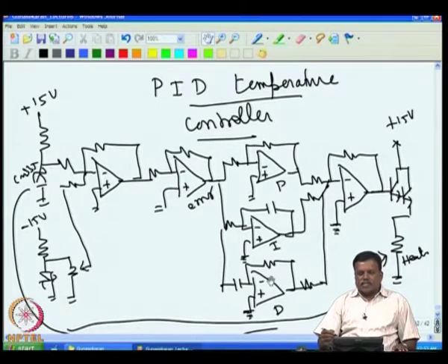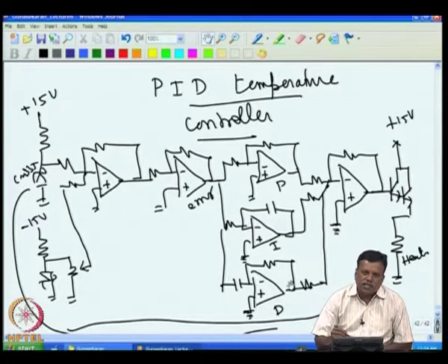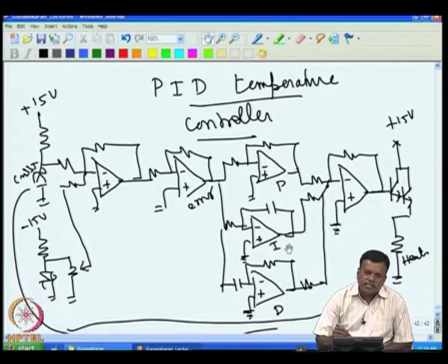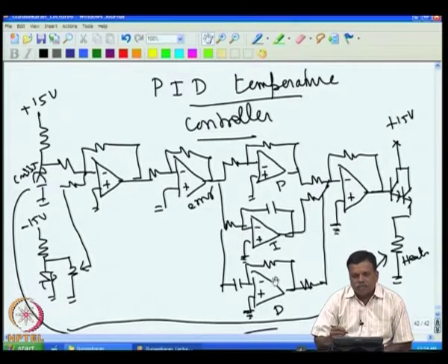Before that, let us try to understand how the differentiator works electronically. What really makes this the differentiator is an ideal element in this case, because many times we will use only P and D, and even the integrator is not necessary if I can give large gain to the system. I can increase the system gain if I add D, because I remove one pole. With only one pole, the system will not oscillate even if I give a high gain. So let us try to understand how the system works.